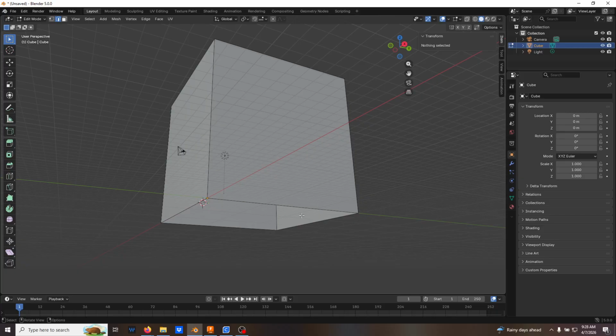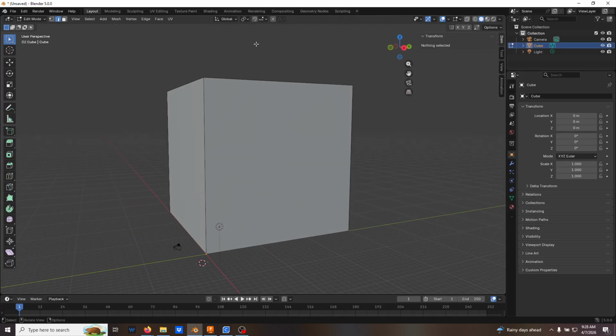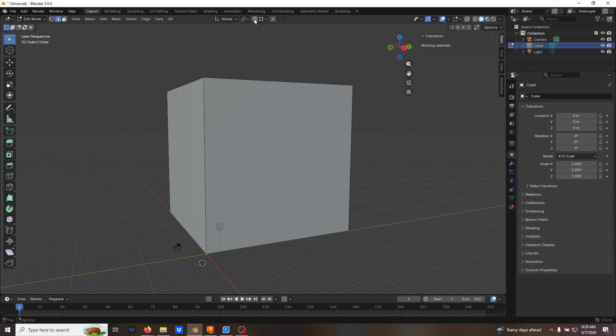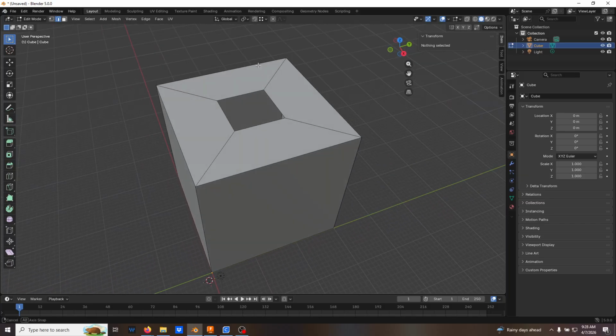Now what I'm going to do here is extrude this down to this edge here, and I could do it directly at 30, but I'm going to use this to highlight some other functionality. If we go up here, you'll see you have this snap base tool, and I'm going to go to vertex. All right, and we can set different snapping. I haven't used any of these other options yet. We'll just go ahead and go to vertex. Also, you can turn this off with this magnet looking thing right here, so you can snap during transform. Oh, Shift Tab is the hotkey for it. Oh, that's nice. Cool. All right, generally what happens is that when you toggle this, it changes whether or not it behaves by default. But I'm going to keep it off, and I'm going to activate it using the Control key.